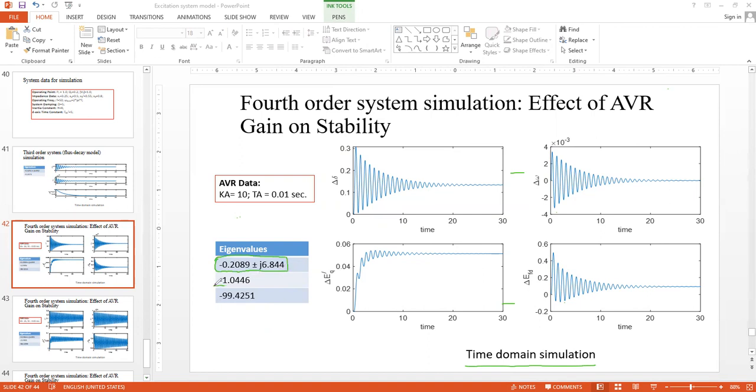So what is the frequency here and what is the frequency here? Basically, they have some j0 part, so they are zero frequency elements. These two roots don't have any frequency term. They have simply a magnitude term. Why am I writing it like this? Because these are nothing but s equals sigma plus minus j omega. For the real roots, you only have the sigma, you don't have any omega. That's why I have written plus j0. So there's no frequency associated with that.